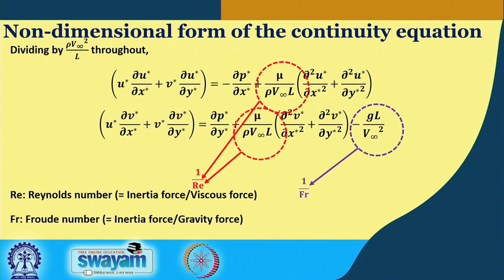What it means is this: any Reynolds number below 2100 will represent laminar flow. That means even if we disturb the flow, if the Reynolds number is less than 2100, the flow will go back to the laminar region. On the other hand, above 2100 there will be a transition zone, okay, where both laminar and turbulent flow coexist.